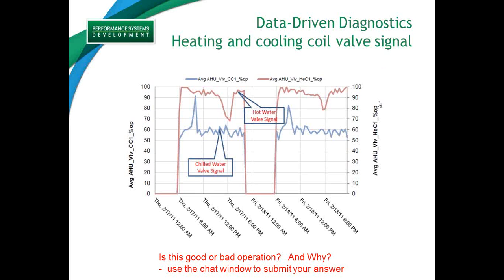But the fact that we have basically the chilled water and the hot water valves fighting each other in order to meet the desired discharge temperature set points, right? Most likely, the hot water valve could be open much, a fraction of that, 50% or lower. And you'd expect to see this probably vary. I mean, it would be nice. I should have the outside air temperature here. That might be helpful as well.